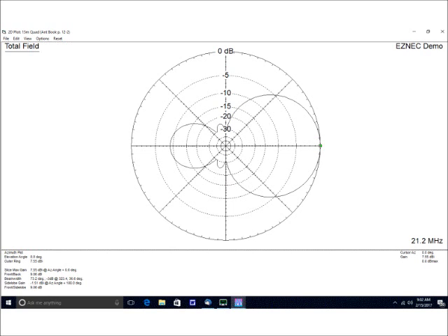So this is what's really going on. All the energy that would have been over on this side has been added to this side. Some of it's still coming out there. You got a little blip coming out there and a little blip coming out there. Antenna gain simply means you've taken a whole bunch of stuff that would normally go out the other side, and you've come up with a method to make it all go out this side. And so, that's why they have a whole bunch of elements on antennas, and gang antennas, and a bunch of stuff. Yes, Dave?